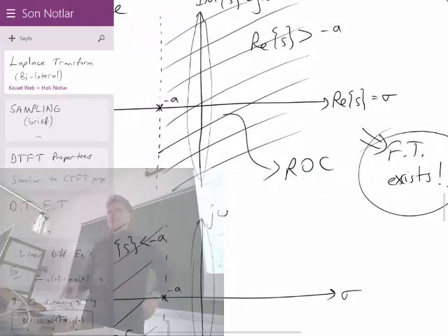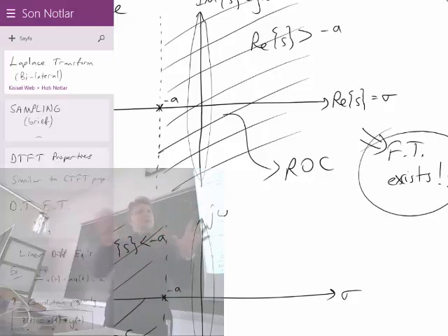Do you remember when I asked you about linear time invariant, causal, stable systems? For bounded input, bounded output stability, I didn't teach you any systematic way if the system is difficult to explain. If you have the impulse response, of course, the magnitude sum of the impulse response must converge. That's a rule. But now you have a better tool to analyze the stability of linear and time invariant systems. It's the Laplace transform. Just evaluate the Laplace transform.